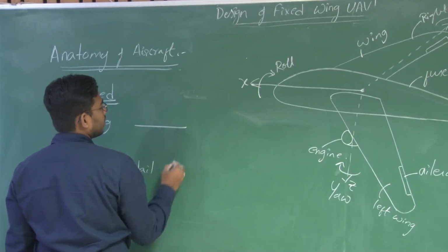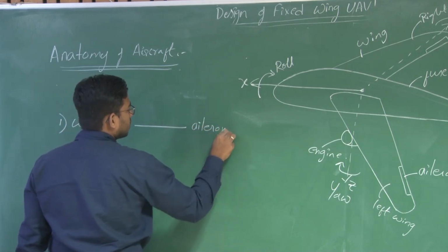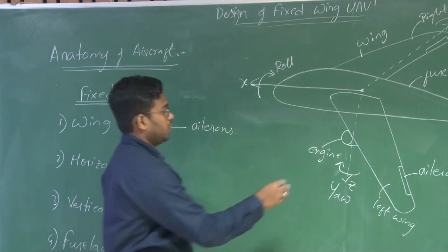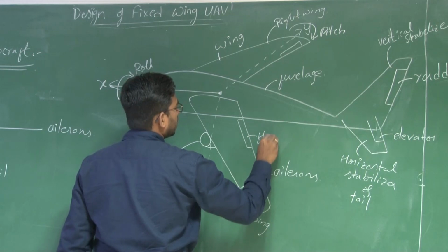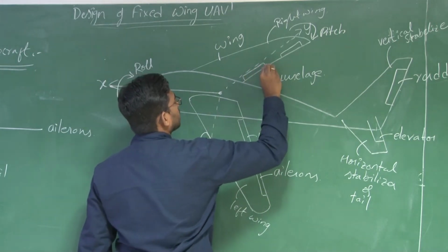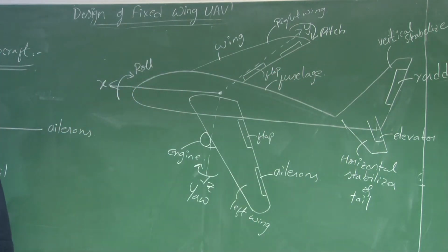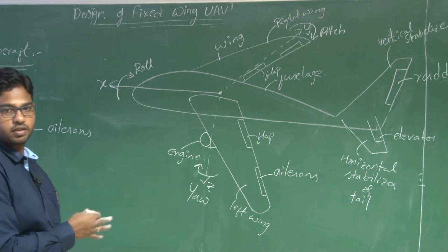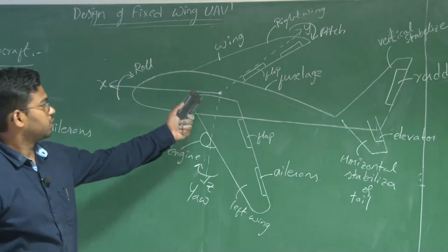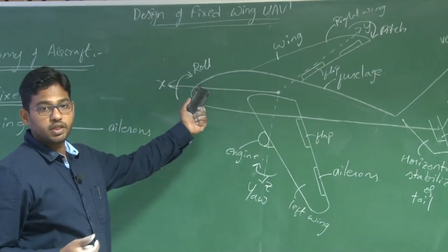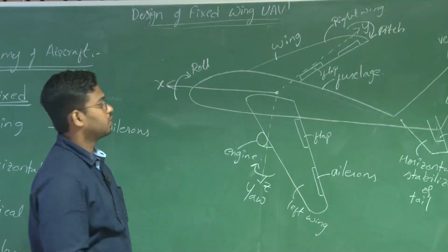So the moving surfaces we have with wing are aileron for control, and you have flaps or high lift devices, flap, which are used to enhance the lift, right? We saw that lift is essential. We nomenclatured just now a force that opposes the weight, right? So lift. If you want to enhance the lift at lower velocities, we need to operate these flaps, right?